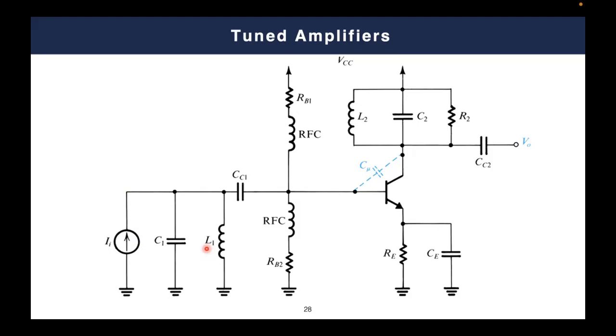You can simply understand it as, we just mentioned that at resonance, the equivalent of the capacitance and the equivalent of the inductance cancel each other. That means that you don't have an impedance. You don't have XL or XC, because XL and XC reject each other.